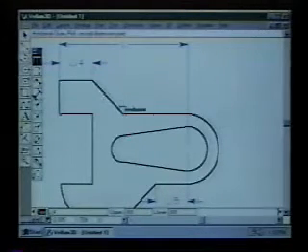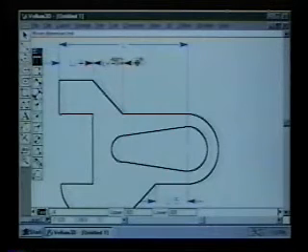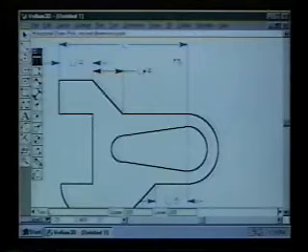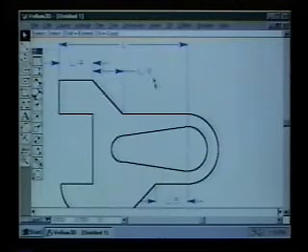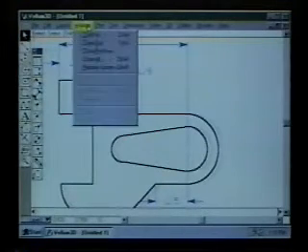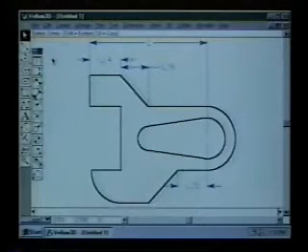And with one additional click, I get another variable which I can actually pull out here or slide it down just a little bit, and we'll call this one L divided by 6. So what this does is I can define all of these variables or all these dimensions with a single variable L, and the relationships are all set up. I'm going to say zoom all to get everything to fit in the screen.